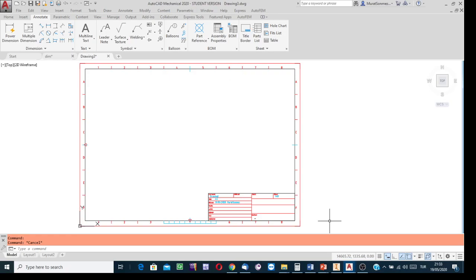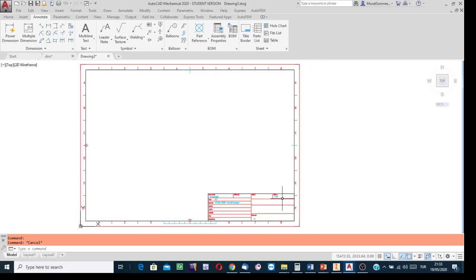Say you show the dimension, the measured distance in the background will be multiplied by the inverse of the scale factor, and AutoCAD will show the size of not the projection but the object, the feature of the object. It is automatic. So having such a template is strongly recommended.